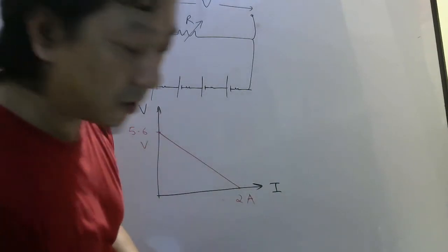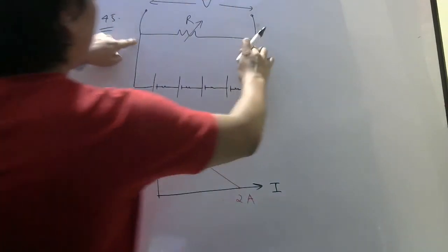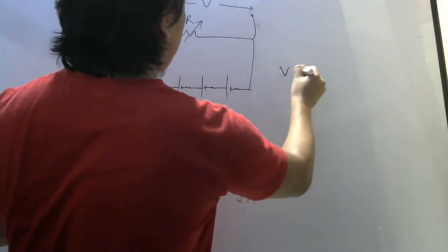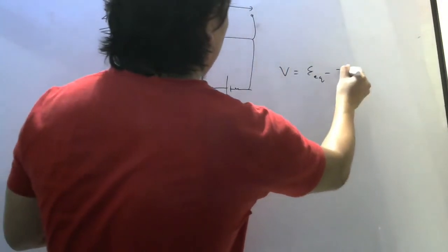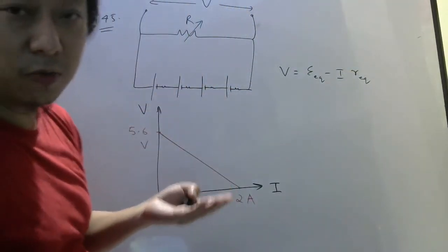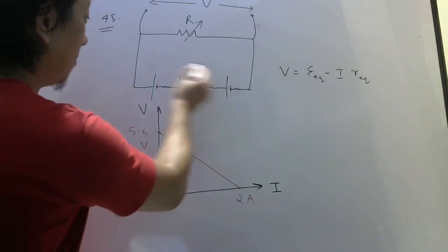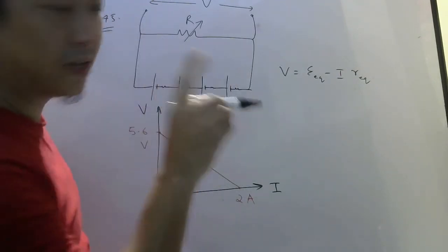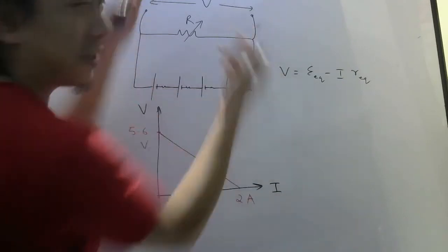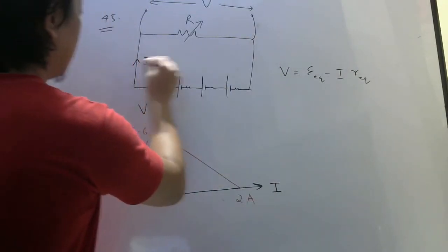Okay. Now, what will be the terminal voltage here? E equivalent minus I into R equivalent. Yes or no? We write, how do we write the V formula? E minus Ir for one cell. So you replace these 4 cells by one cell and write the terminal voltage for that cell. Understood or not? Okay. Current will be I because it is series.